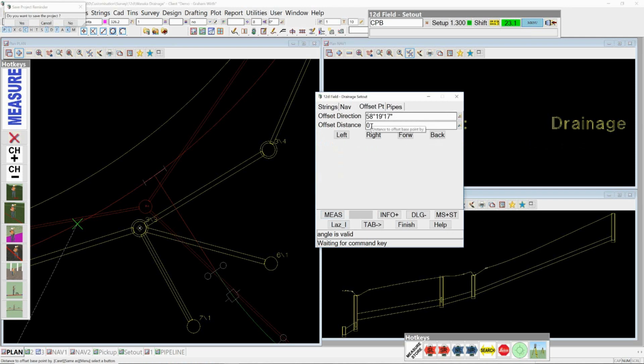So in most cases when surveyors have been setting out pits, they put in 2 pegs that are 2 metre offsets in a line, so that the excavator, or the operator or the drainage personnel, can come along, dig the pit out and place the pit box in, and then allow you to line it up. Particularly in the case of subdivisions where you're aligning it to the lintel in a curb and gutter situation, or in a graded drain where you're aligning to the drainage line for a square pit. In this case, we've got circular manholes, so it's not really relevant, but we'll show it anyway.